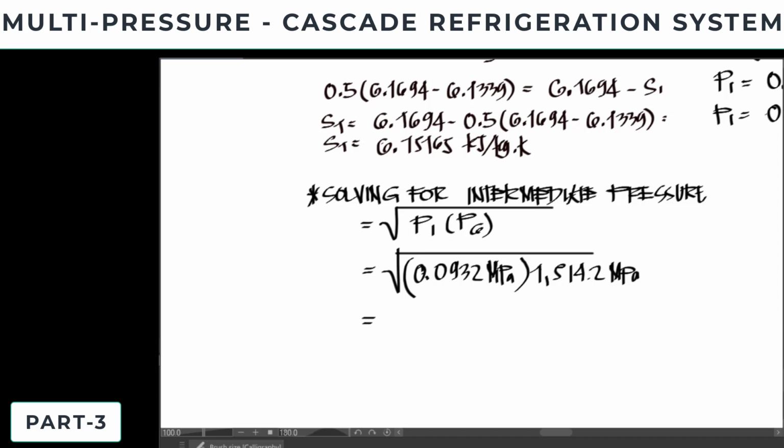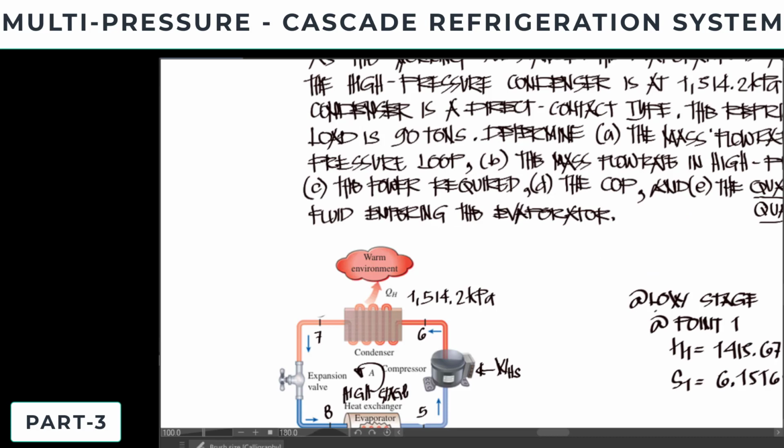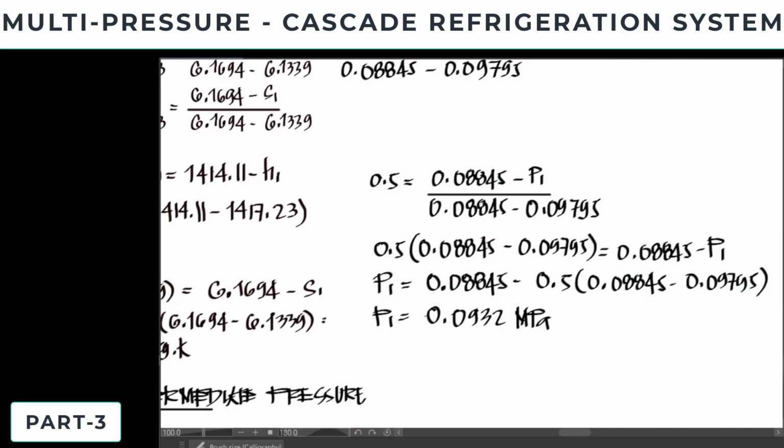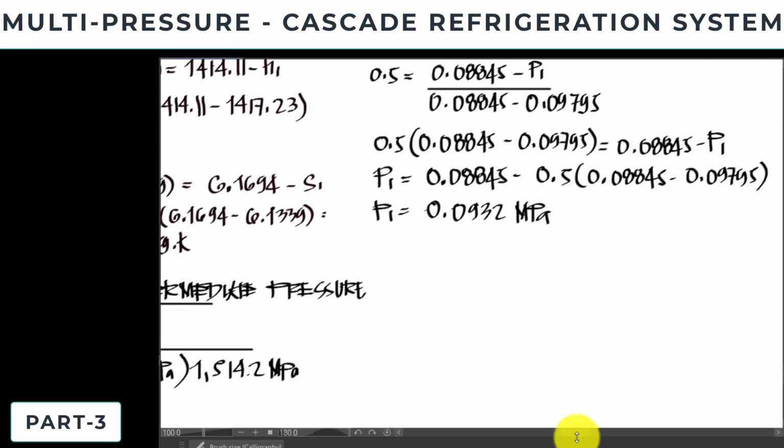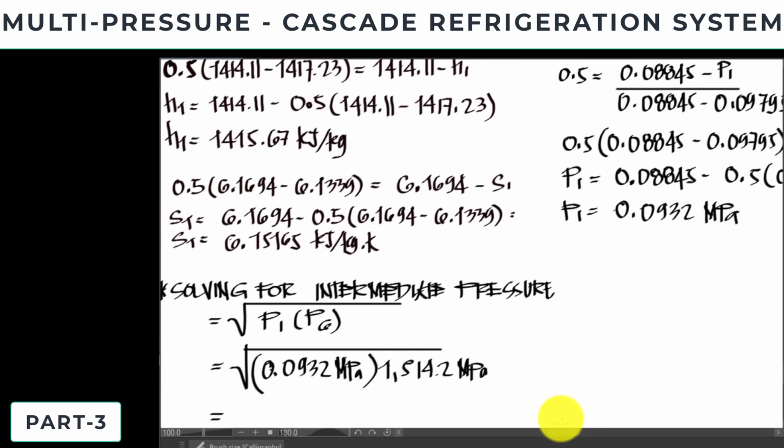Okay, a correction here. I didn't notice that is why my value was too high. This is given in the problem in the unit of kPa. So let me convert this. This is equal to 1.142 in terms of megapascal. So that is the reason why the intermediate pressure was too high. So let me correct this one.